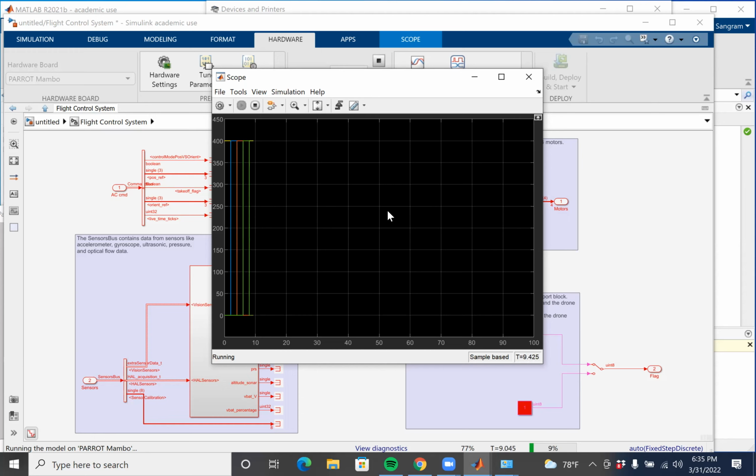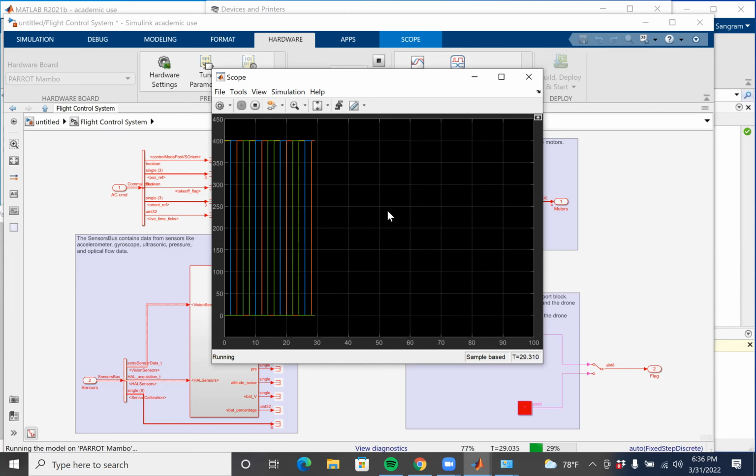So now I want you to notice what? Basically, it is sending 4 PWMs, but those PWMs are not sent simultaneously. Those PWMs are phased, so that what you have is, check this out. This is the first motor, second motor, third motor, fourth motor. Are you with me so far?